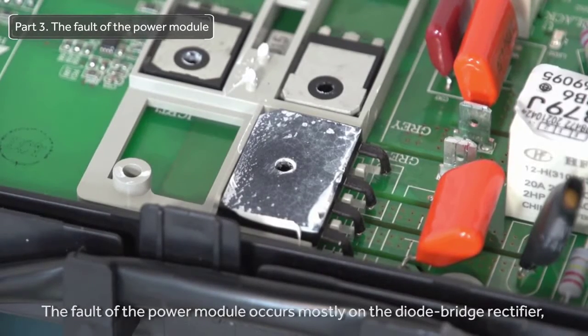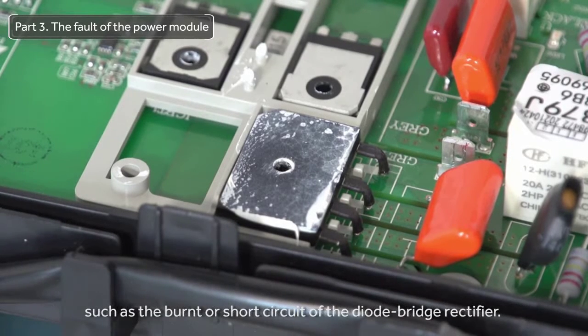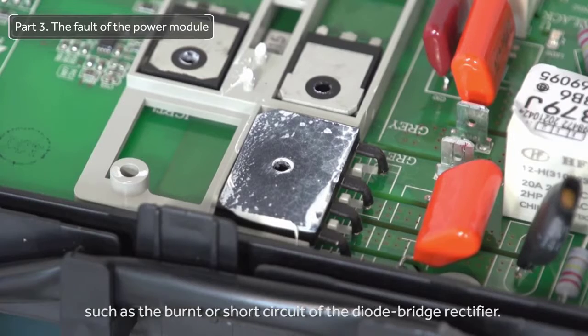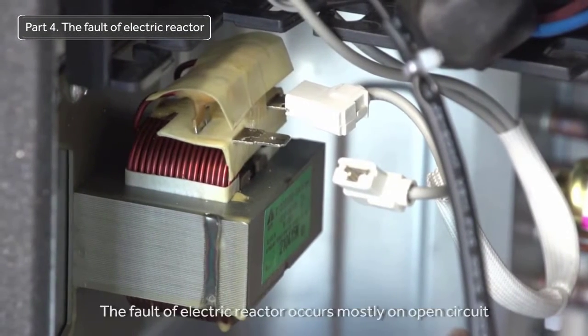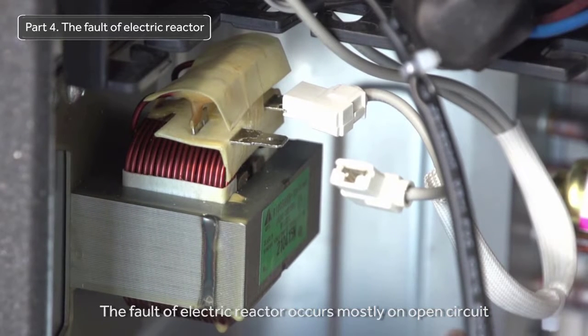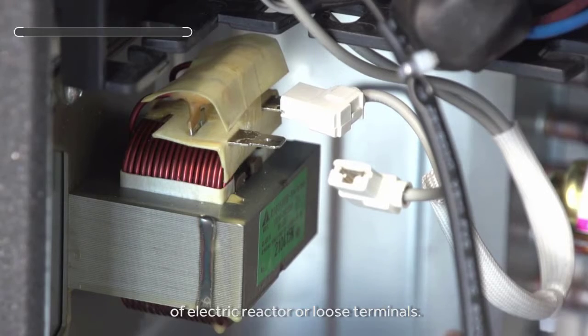Part 3. The fault of the power module. The fault of the power module occurs mostly on the diode bridge rectifier, such as the burnt or short circuit of the diode bridge rectifier. Part 4. The fault of electric reactor. The fault of electric reactor occurs mostly on open circuit of electric reactor or loose terminals.